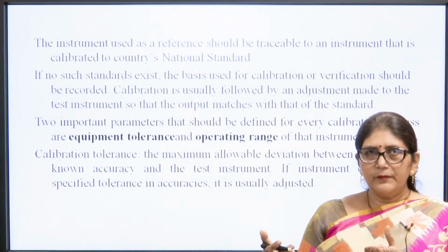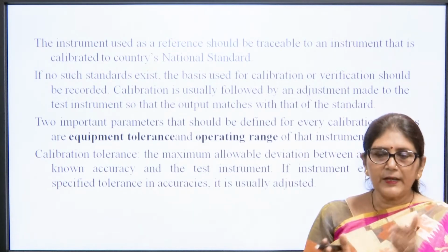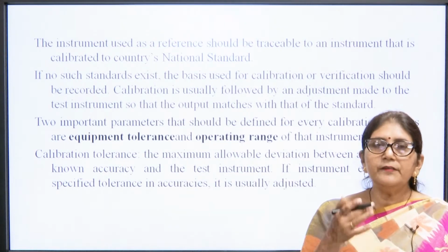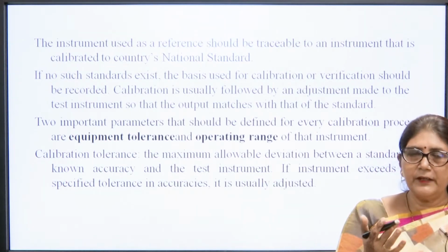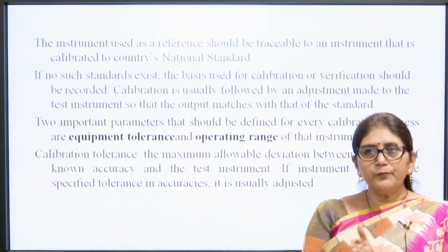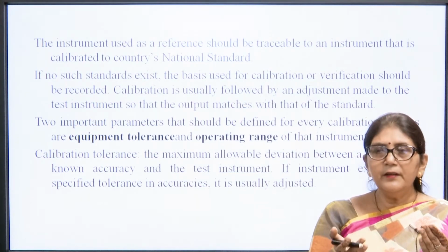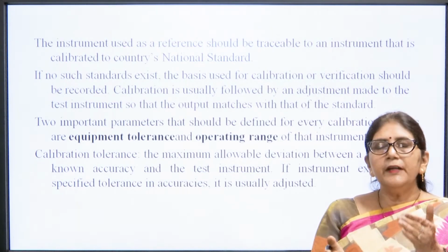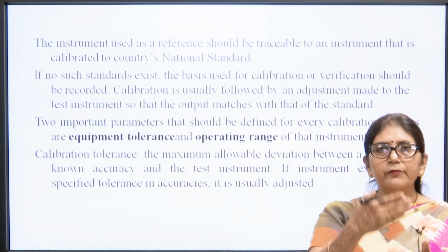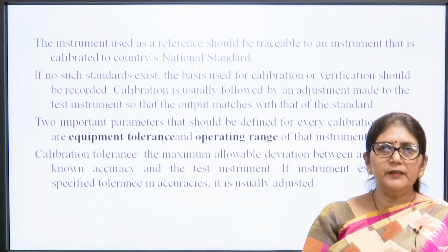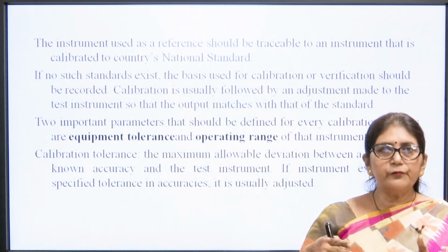We have to calibrate our instrument with the country's national standards, that is the reference. So, we will send 10 instruments there, and when these 10 instruments are calibrated against the national standard, the national laboratory will send us a report of what the accuracy of our instrument is and whether our instrument is useful or not.